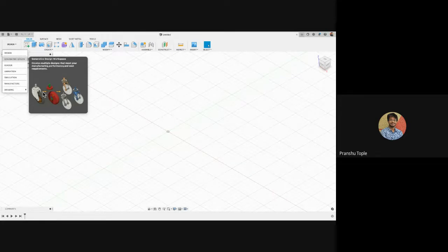You can see that there is this caster wheel, but this caster wheel doesn't need to have this complete steel part. What does it need to have? It just needs to have this green part, which is the rotating part, and this is the axle of the wheel. These are the most important things, and it should not collide with these red things. So if we tell Fusion 360 these things, it will make an optimal design.